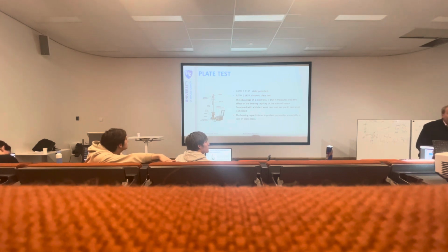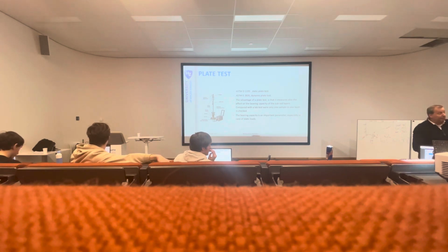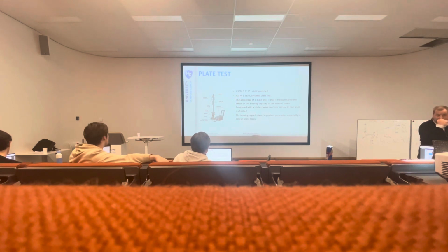So for example, when you put 5 centimeters of sand, and underneath that sand it's a very weak clay, you don't have the same bearing capacity as a sandy soil, because the soil beneath will have an impact. If you take out the sand, test the CBR, and say, oh, the subsoil has a good bearing capacity. But with the plate test, you also check what is beneath that small top layer. That's the advantage of EV1 and EV2 measurements.